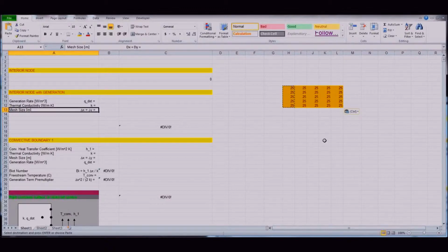If you recall the way we derived the equations for the finite difference, we had nodes on the surface, so for a system with 3 grid points, that would be 2 delta X. Essentially, the number of cells you need is determined by the length of your object divided by the delta X that you set.